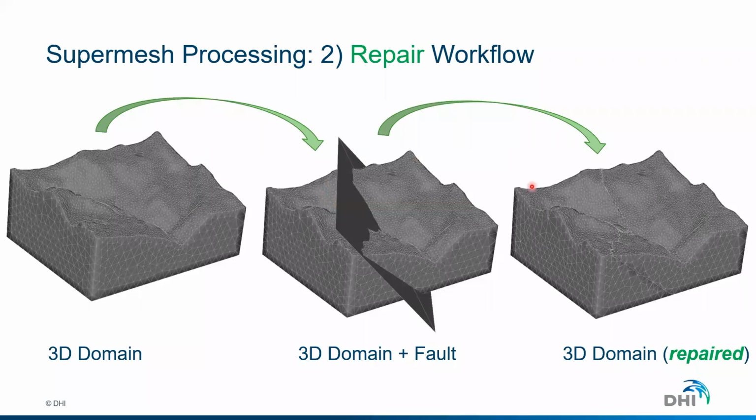Then we call the repair, and the repair tool has a possibility, which is optional and up to you, to discard parts of the surfaces that are outside the domain. So it has the possibility to cut the plane and then throw away what is not inside the box or the domain. And it will reconstruct the surfaces in a way that acknowledges the intersection between this box or domain and the plane.